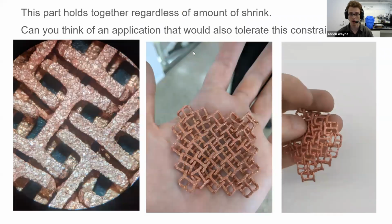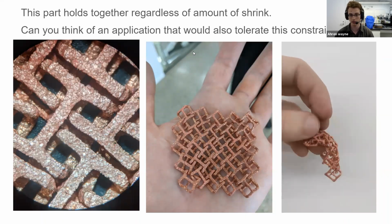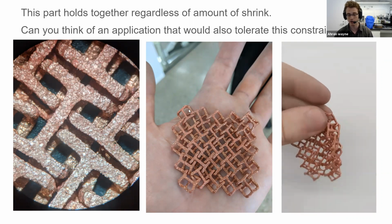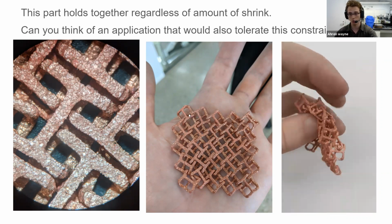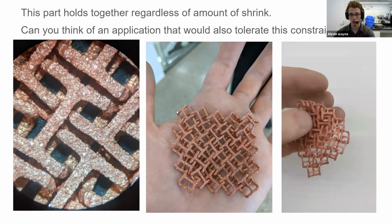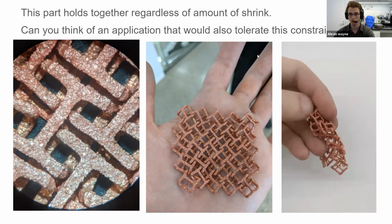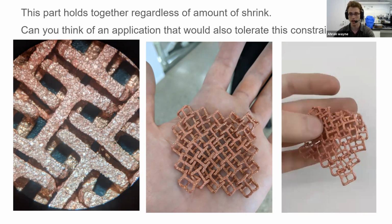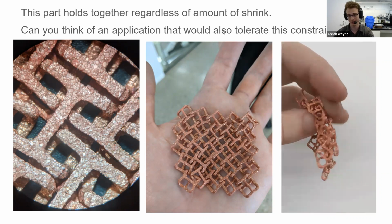Here's an example of a part that would hold together even if it shrank a lot or if it shrank a little, because all of the links are completely interconnected. There's no gap for them to escape through. So whether or not this was green or shrunk a little bit or shrunk a lot, it would still be chainmail. So if you want to print a mesh, it's kind of an ideal application for this method. And if you can think of another one, I would really like to hear it, because I'm always interested in other applications.